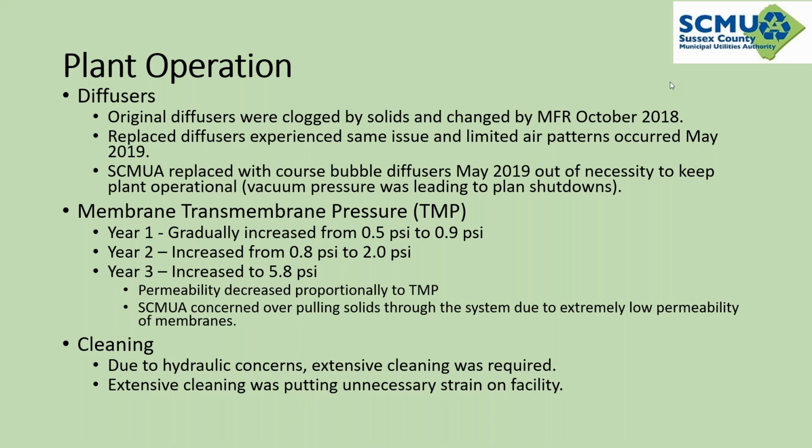You get to the point that obviously your permeability decreases proportionally to your transmembrane pressure increasing. So now that our TMP is increasing, our permeability is decreasing. Now we're concerned over pulling solids through the system due to the extremely low permeability of these membranes.